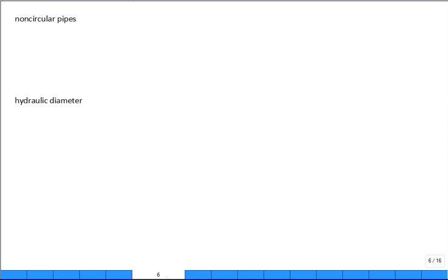So what about non-circular pipes? Let's say you have ducts or an ellipse, professor. Do they really have ducts and ellipses like that, rectangular for airflow and water flow? Yes, they do, especially for airflow systems. A lot of the reason is you typically put the airflow in the ceiling. Between the bottom of the floor above us and this drop ceiling, there's a lot of electrical and plumbing, and there's a lot of HVAC, okay? And they need to fit it into that tight space.